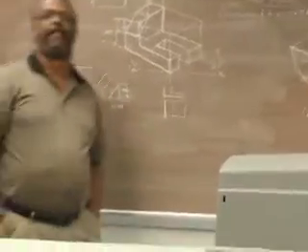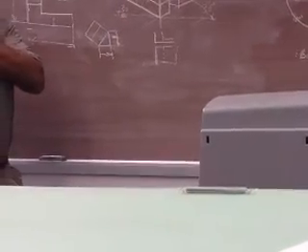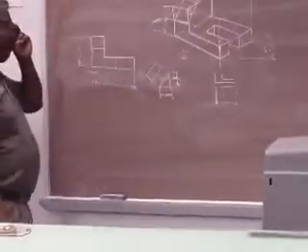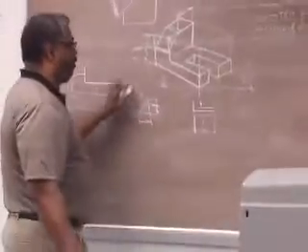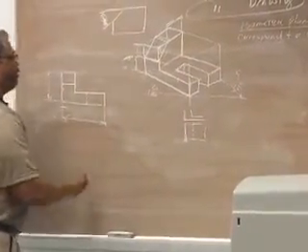Yes, sir. Do you need to do those lines, the hidden and the visible lines, in both the top, front, and rear? Correct. Wherever you lay out your views, if your edges appear visible in a view, they should show up visible. If they appear hidden, they should show up hidden.